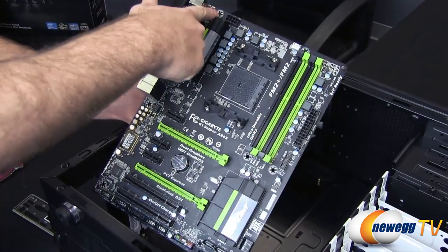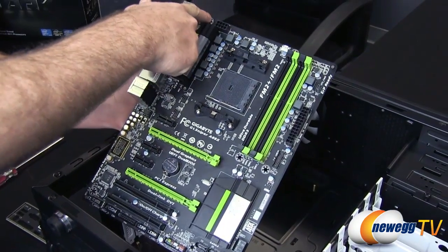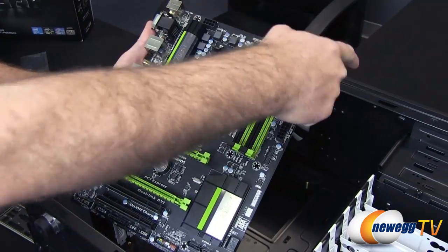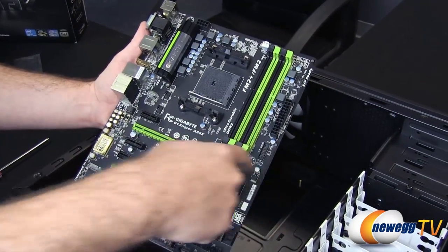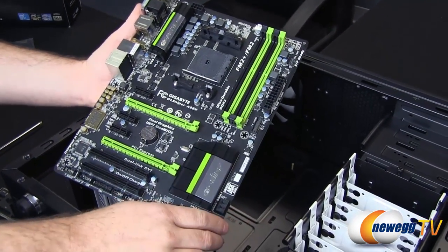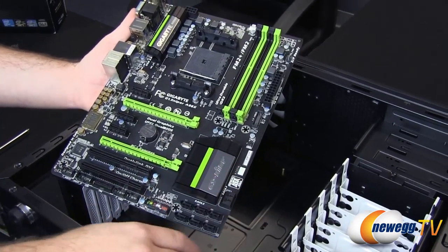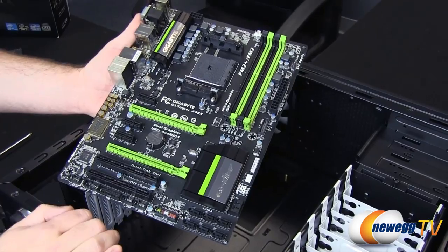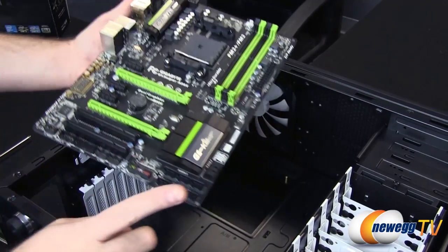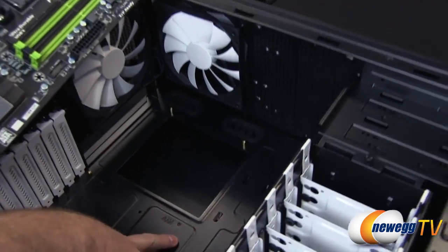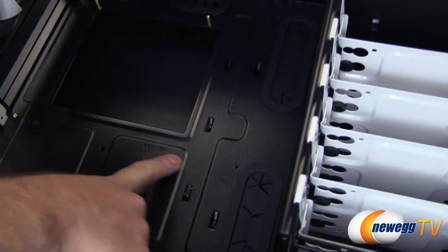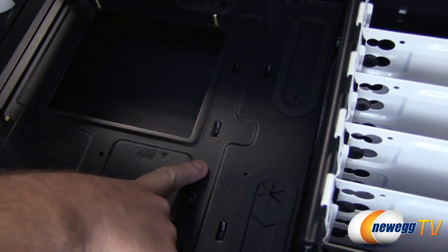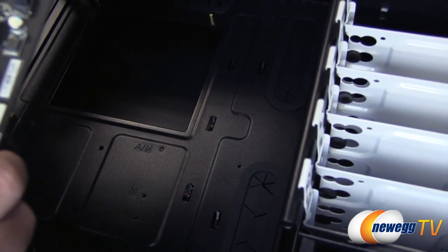Those are these little standoff holes right here. So with standard ATX, you'd have 1, 2, 3, 4, 5, 6, 7, 8, 9. This motherboard, since it's not quite as wide, only has 7, which is fine, that's how it's designed. But unfortunately, we're missing 1 standoff point in our case. We have this one here, but we don't have an in-betweener right there. So I'm going to show you guys a way to work around that.